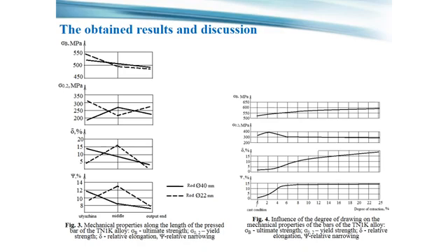Upon visual inspection of the bars, it was found that bars heated to about 1000 degrees and pressed at high speed have cracks on the surface. Reducing the heating temperature to 880 to 900 degrees, the pressing of the bar leads to underpressing of the blanks.